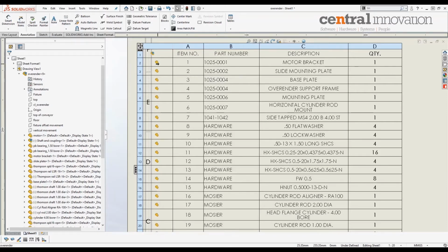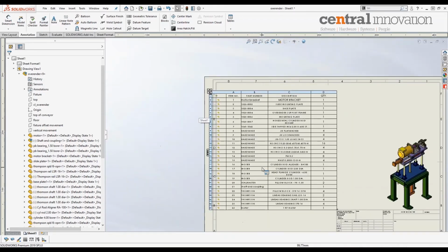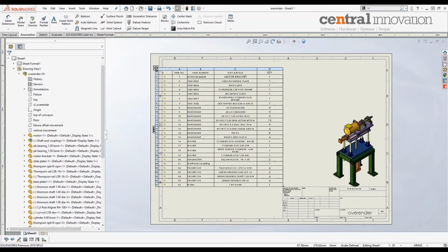Whatever input the user gives here is going to be populated in the part number values here. But from the bill of materials as well, since our topic is bill of materials, we can control this behavior. If we expand this little bar and right click here, we have this component options, and that's pretty much the same window that we just saw at the part level. We can change it to document name, a user specified name, or configuration name. So let's say I change it to document name, it'll switch to the component file name.